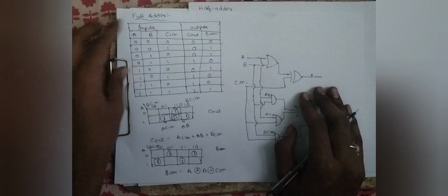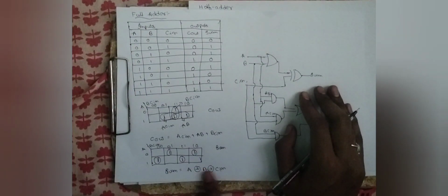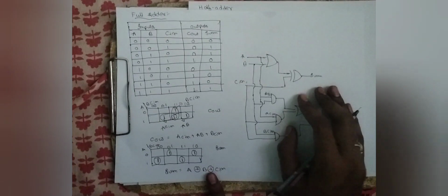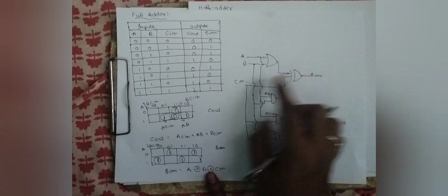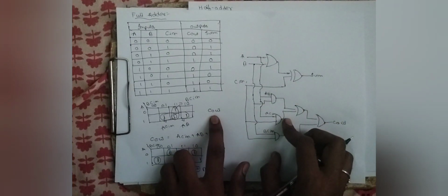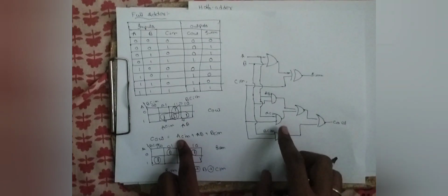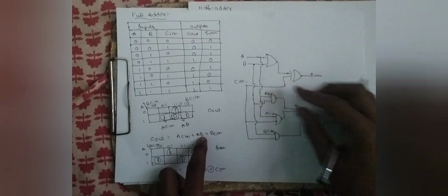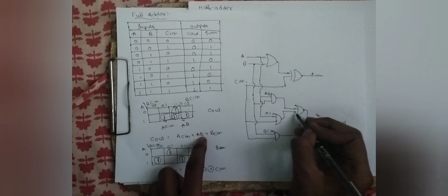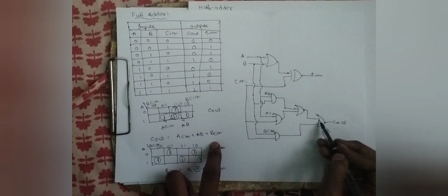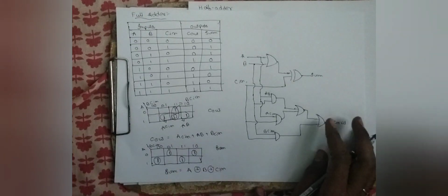So this is the circuit diagram for the full adder circuit. As we can see, the sum expression is A XOR B XOR C in, so according to the expression we have drawn a circuit. Next, when we come to the C out circuit, here AC in is the gate of AC in, and AB is the gate of AB. These will combine to give an OR gate, and the final expression is seen. So this AND gate and this OR gate will come to give another OR gate. So this is the circuit of the full adder.